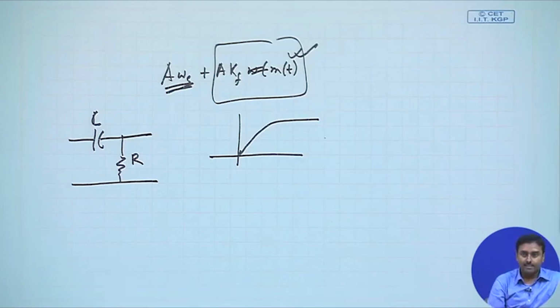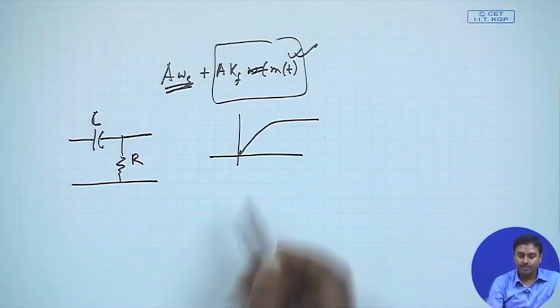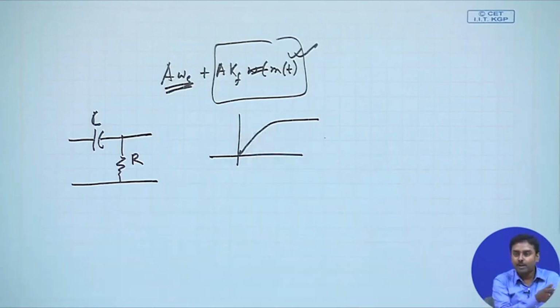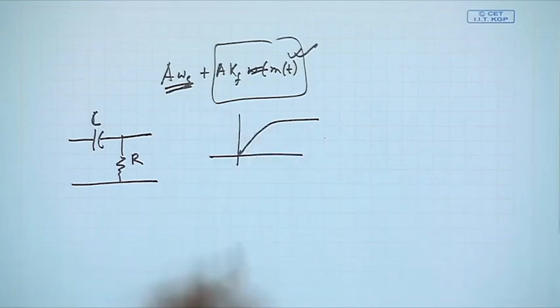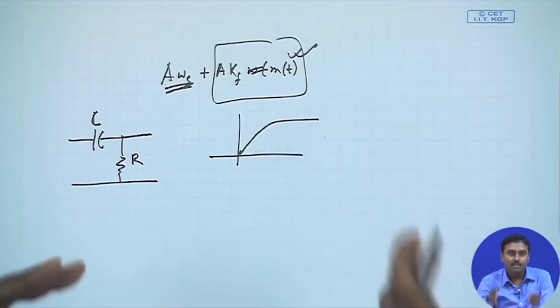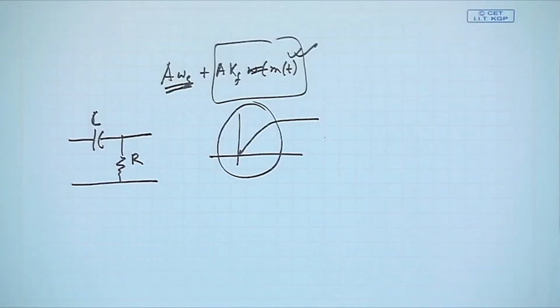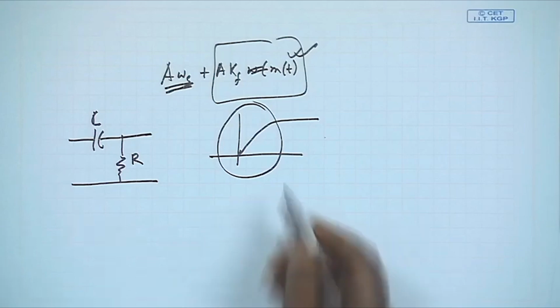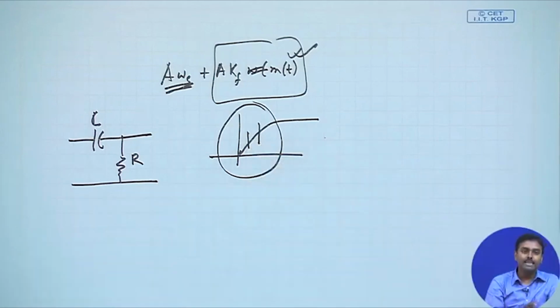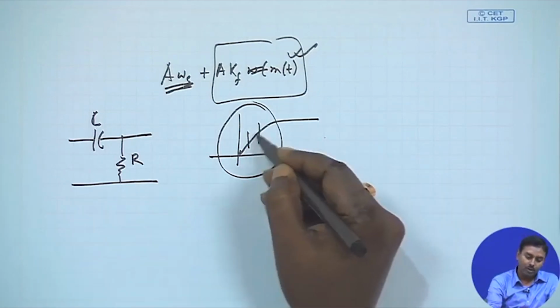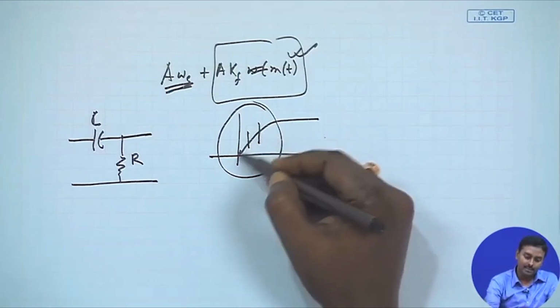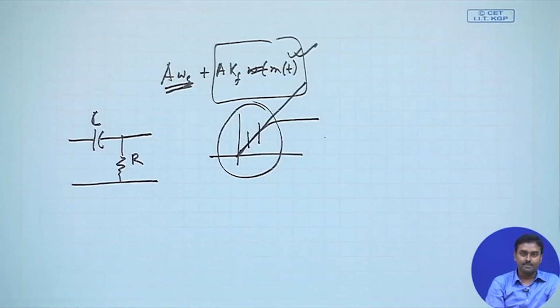But in a high pass filter, generally we are not bothered about this roll off, we want to neglect it. In a high pass filter we are more concerned about where the filter response is flat, but for FM demodulation we are bothered more about this roll off. So, we want to see where exactly it remains linear, that is where it almost behaves like an ideal differentiator.